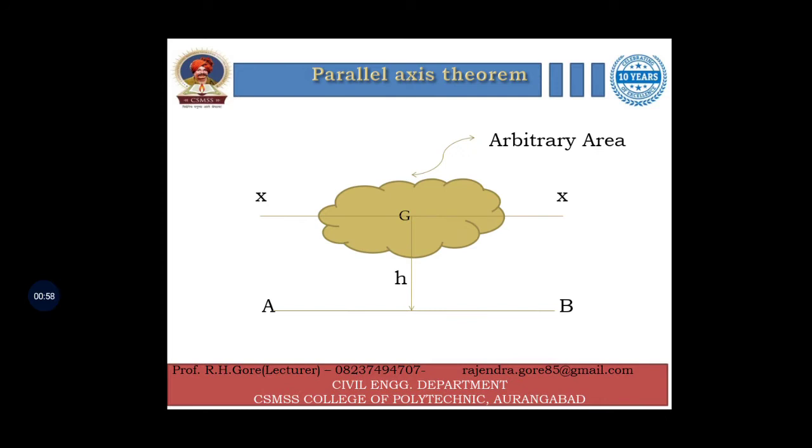Consider an arbitrary area having cross-sectional area A, and a horizontal XX axis passing through the CG of the section, and a parallel axis AB at a distance h from the centroidal axis. So the moment of inertia about the parallel axis AB is equal to the moment of inertia about the centroidal axis plus the area of the section into the square of the distance